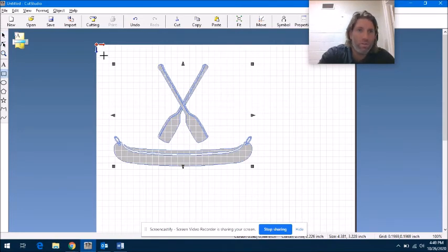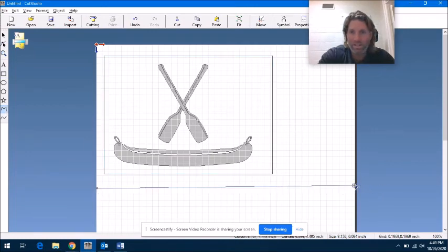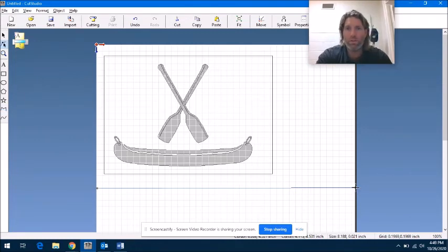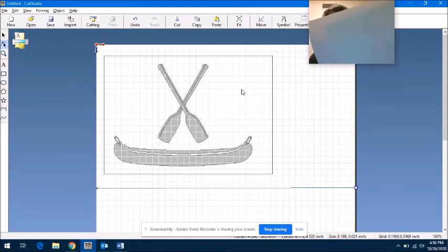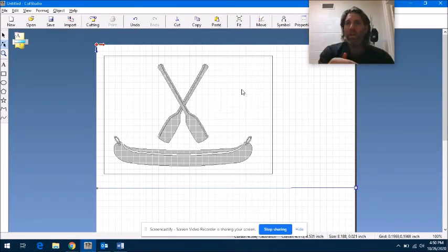So for this situation, I draw a box around the whole shebang, and I draw a line at the bottom. So after my item is done, the cutter will cut right across, and then I know where the next person can start from. If I look where my mouse is swinging around here, this white part, I actually use my weeder to remove that part. So if I do my image, if I etch it, I'm going to have clear paddles and clear canoe and a white cloudy background.